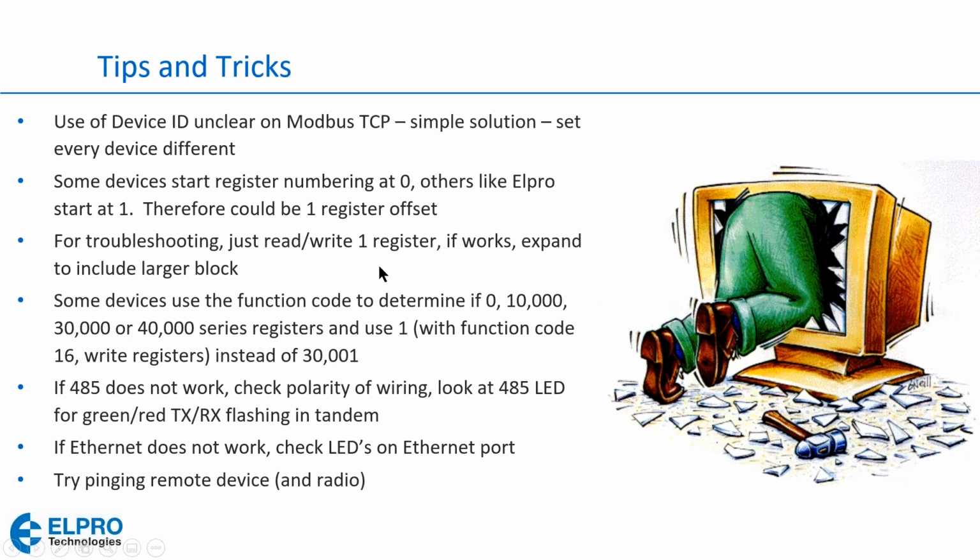They cannot be uninitialized. And in our 415 products and the 215, etc., we have something called fail-safe blocks. Part of the fail-safe function is that it allows you to initialize a register upon power-up. So you can say, I want a value of 1,000 in all of my analog inputs upon power-up.